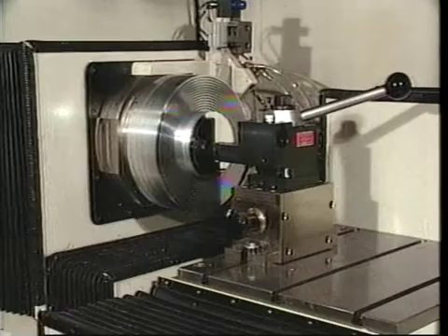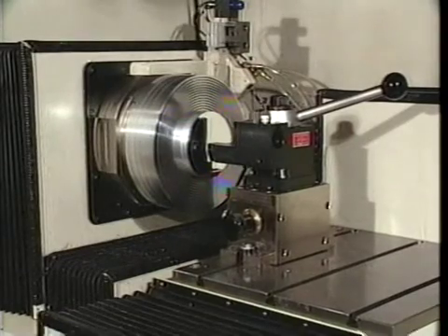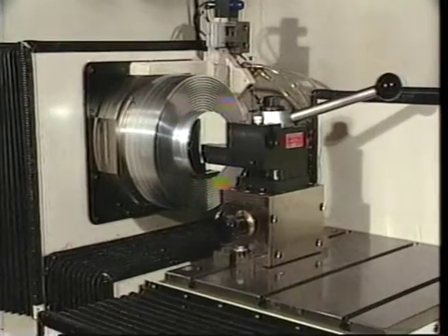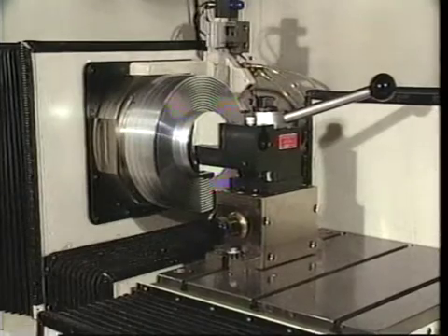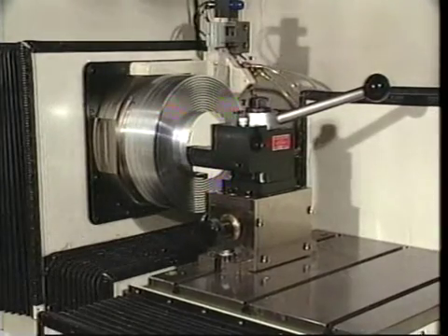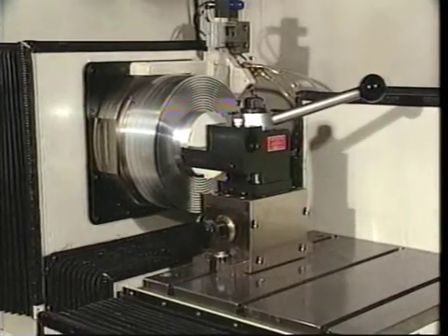The objective of this lab is to demonstrate the reversal technique for straightness of motion measurements. Machine slides or carriages are theoretically single degree of freedom devices permitted to move along only one axis. In practice, measurable motion occurs in all directions, thereby introducing discrepancies between the desired and actual positions.